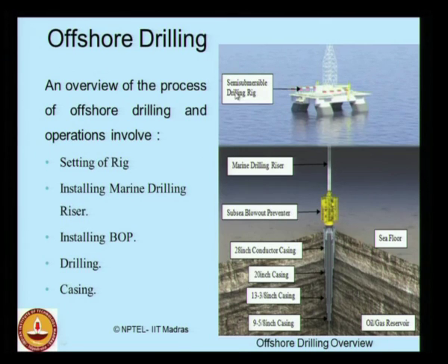I have a semi-submersible drilling rig which is being used for drilling at a specific field. This is basically the drilling case. This is what we call a marine drilling riser. I have provided here a subsea blowout preventer, which is shown in yellow color. This indicates the sea floor.